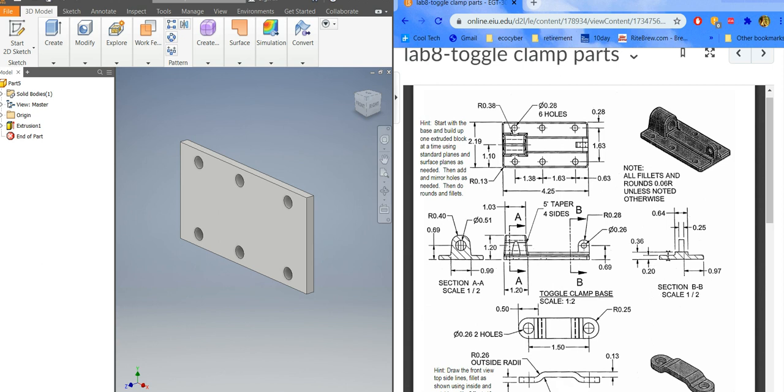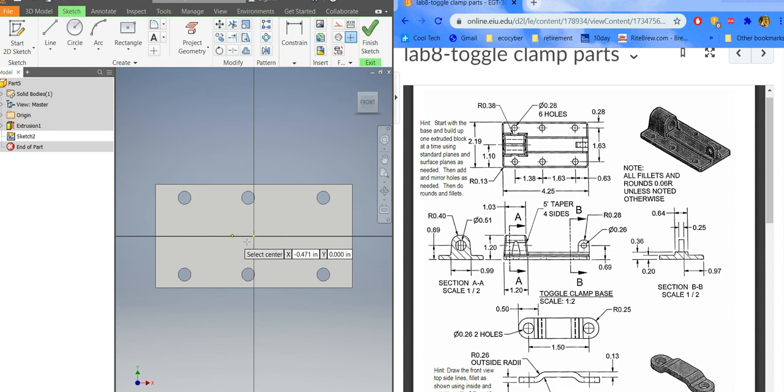So let's do this next. Everything on this thing is just, like I said in the video, a bunch of rectangles that are extruded up. So this one's 0.64, okay, and it goes up this minus that, and its full length is fine. Okay, so right click, new sketch, rectangle. Okay, the width of it was 4.25, tab, 0.64 on this one. Okay, so it's an actual.